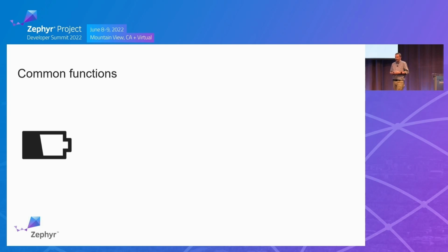First, we have the battery. The EC controls whether the battery is charging when the laptop is plugged into power, or discharging when it is not. It monitors the battery's charge so that it knows when it is almost empty or almost full. The EC can also track the battery temperature and get a feel for the health of the battery.